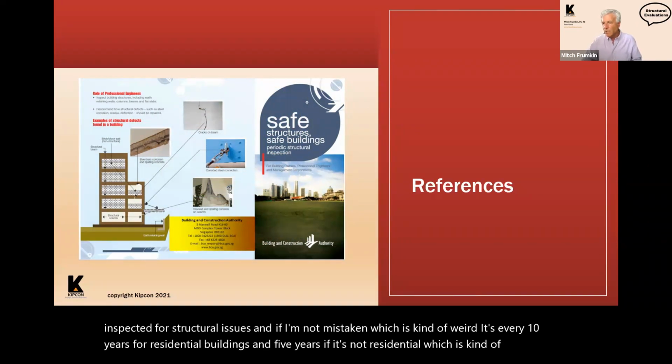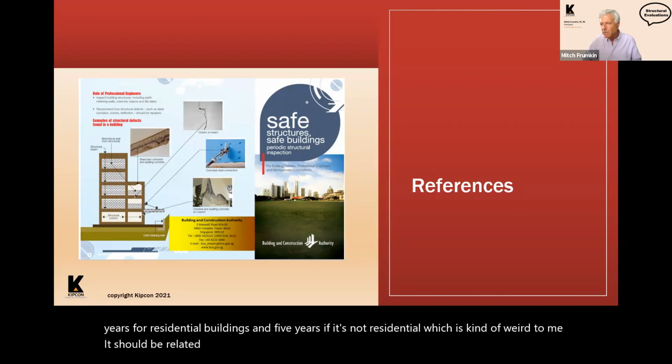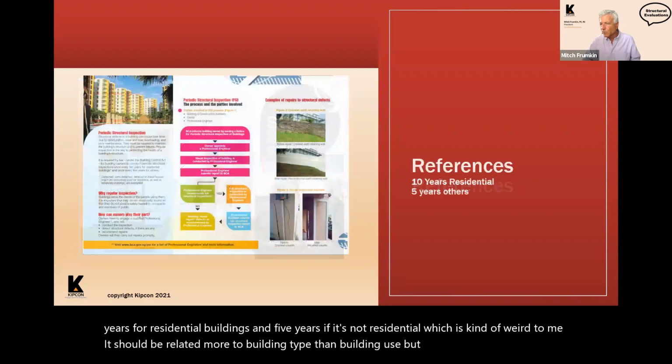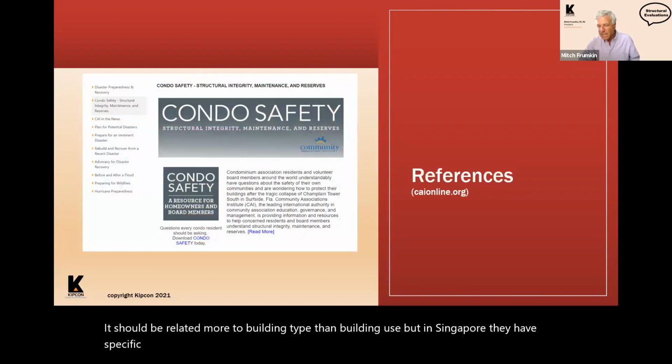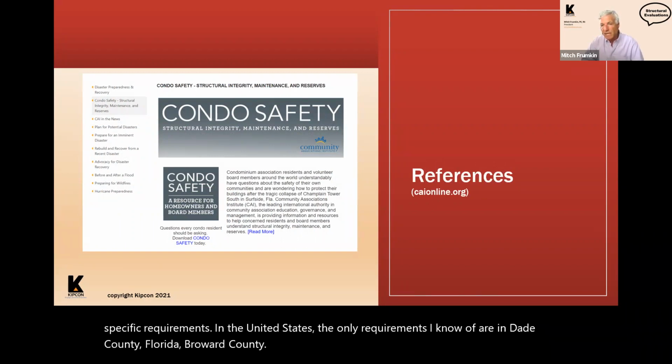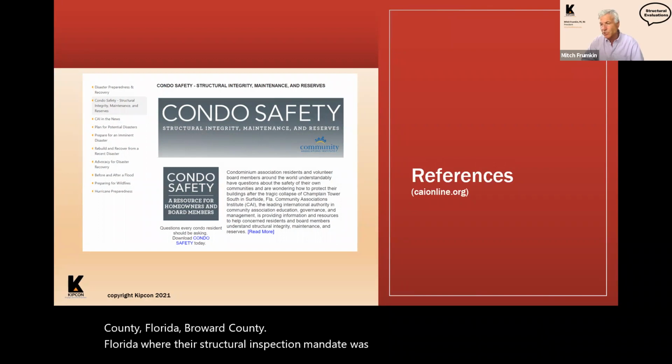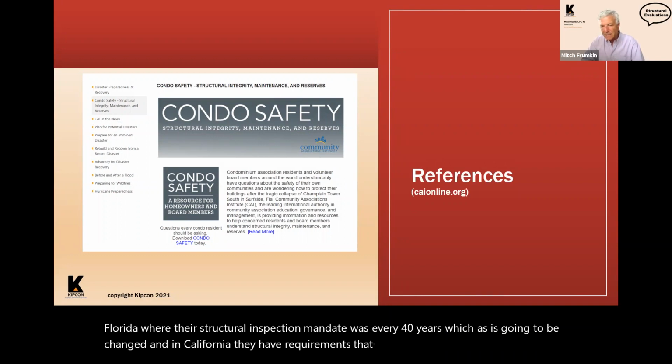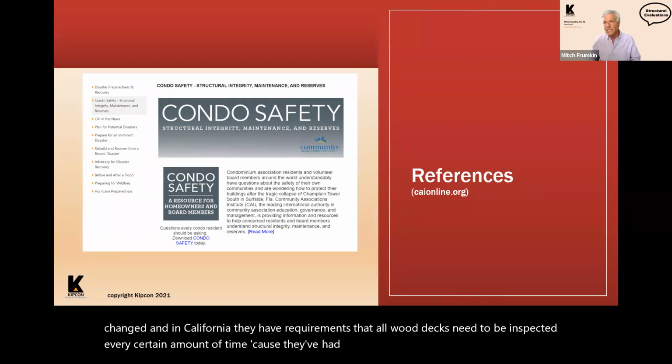To me, it should be related more to building type than building use. But in Singapore, they have specific requirements. In the United States, the only requirements I know of are in Dade County, Florida, Broward County, Florida, where their structural inspection mandate was every 40 years, which, as you know, is going to be changed. And in California, they have requirements that all wood decks need to be inspected every certain amount of time because they've had failures of wood decks.